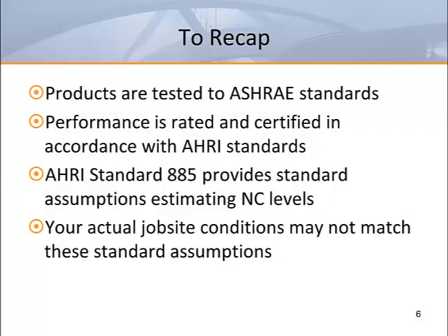All manufacturers test terminal units and air outlets to AHRI standards and then publish the performance ratings in accordance with AHRI standards. AHRI standard 885 provides standard assumptions that all manufacturers should use to estimate NC levels for catalog data. These same assumptions should be used as the defaults in selection software as well. It's always important to remember that your actual job site conditions may or may not match these assumptions. Your ceilings could be better or worse, or you may not have a ceiling at all. Extra care must therefore be taken when estimating sound levels in spaces other than standard office environments.